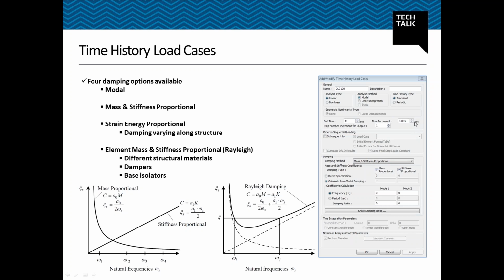However, the natural frequency of the train can be quite influential, so it is required to try a smaller time increment and see if the result converges or not. And for the frequency for mode 1 and mode 2, mode 1 will be using the frequency of the lowest mode, and mode 2 will be using the frequency of the highest mode after eigenvalue analysis.